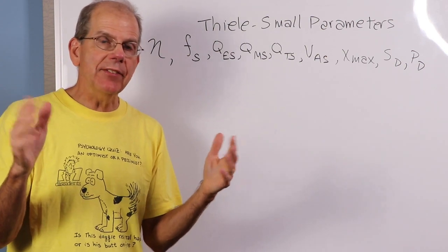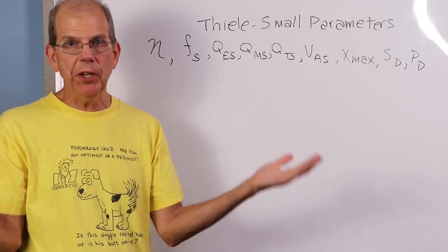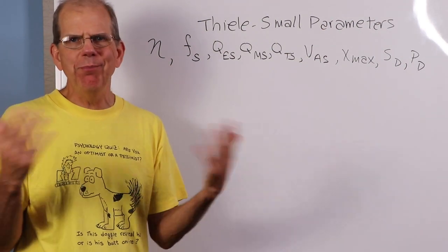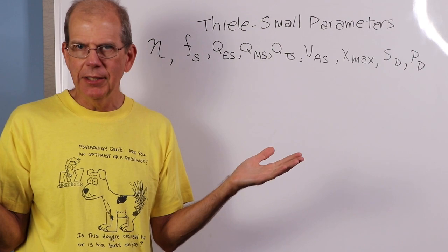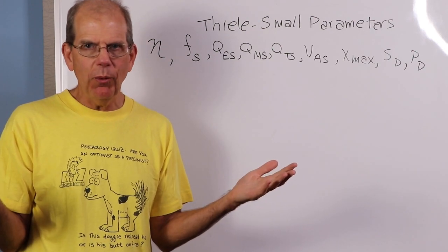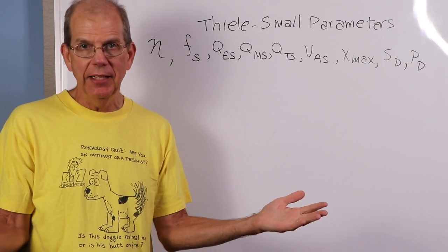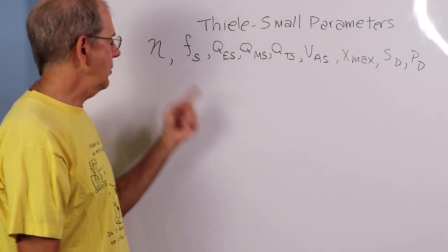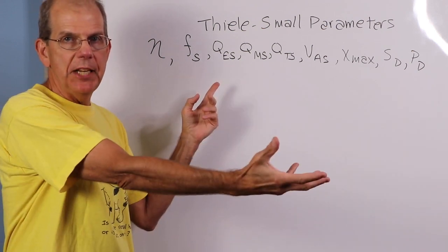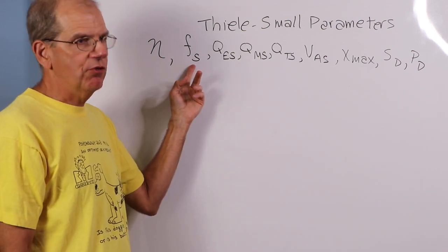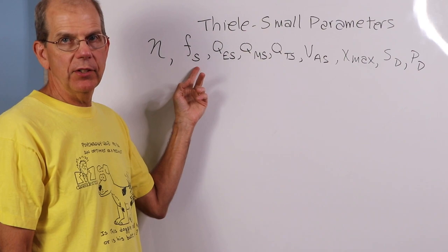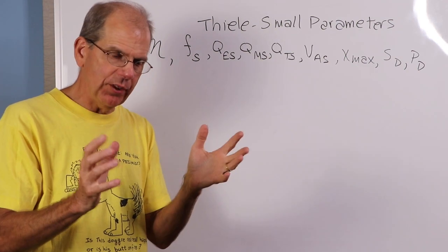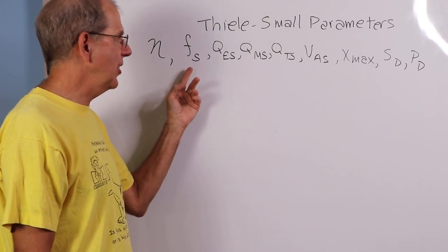But it's not the case that if I walk into a classroom with 20 people, the tallest person must be the best basketball player, right? That's not the way it works, because there are other things going on. Yes, it's an indicator, but by itself it doesn't tell the whole story. So for deep bass extension, you generally want a lower FS, which you will get with transducers designed specifically for those applications. But by itself, it's not the whole story.